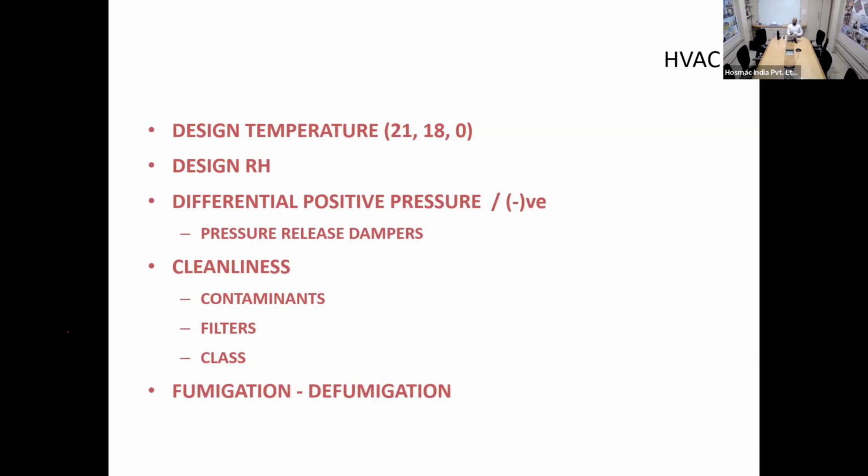Cleanliness, of course, you have to maintain. So, there is a school of thought which has been speaking about cleanliness in terms of class 10, class 100, class 1000. Not a terminology that we in healthcare for operating rooms use, very often. It's something that is more commonly used in pharma. For us, it is important to ensure that we have a particle count that does not exceed 100. So practically, we are talking about class 100 conditions under plenum. So very important to ensure that we have filter integrity met. I'll show you a picture. Maybe that will help us understand better.